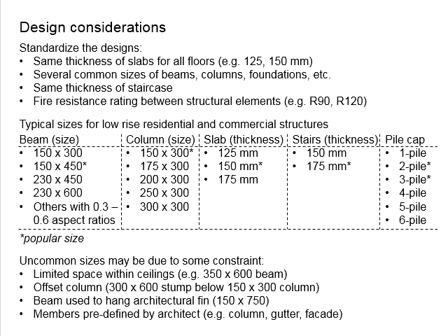What you can do here is you will need to limit the numbers of the sizes to be applied throughout the entire building. This is so that the checking can be done quickly. Some require measurements, some can be quickly observed through visual inspections. Now that you know the reason behind it, we're going to look into every single part of it. Try to standardize the thickness of the slab for all floors to avoid confusions.